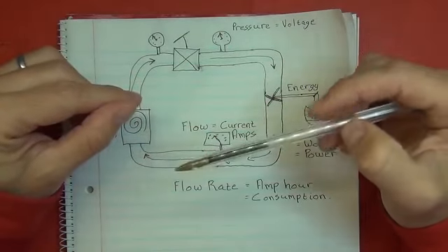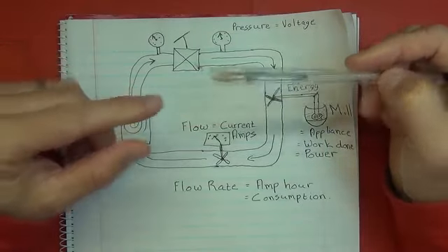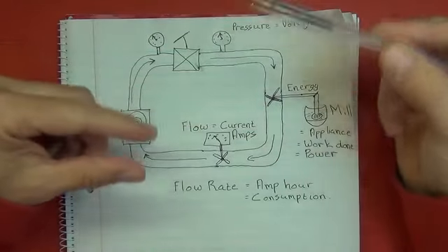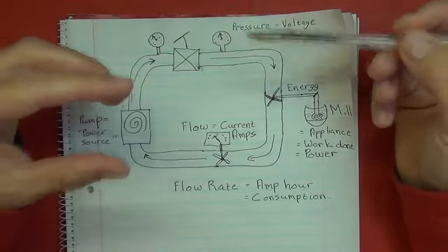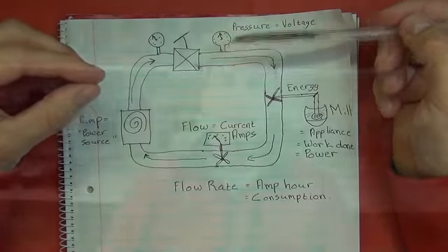So you can transfer high voltage at low current, so you don't need thick wires, you've got less loss, and then you transform that back to your normal voltage when you get to your house.